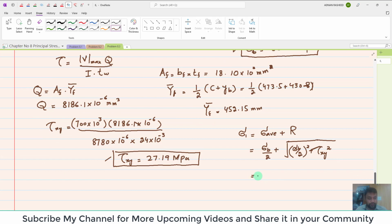You have the value of sigma B, which is equal to 86.06 divided by 2 plus, not minus, because we are going to find the maximum normal stress, the square root of 86.06 divided by 2 whole square, and tau xy is 27.19 square.